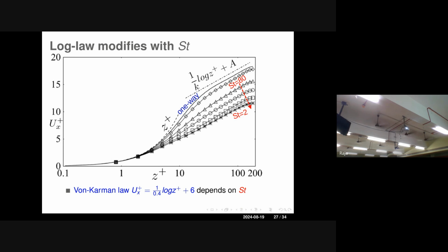Correct. But because these are inertial particles, you need to say what the velocity is once it has crossed over the wall. We don't do that. What we do is immediately flip the velocity. So the normal velocity is reversed, and the tangential, nothing happens to it, so there will be an elastic collision, right? You can say that, but you are not doing anything about the particle. So I'm assuming this is very dilute, with less than 1% volume fraction, so interparticle collisions are nothing to bother about.